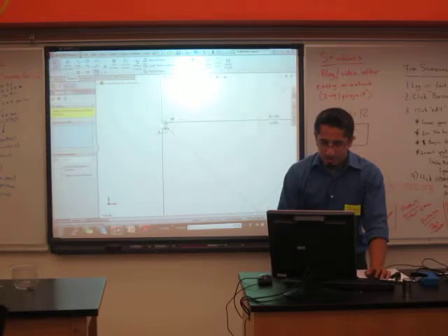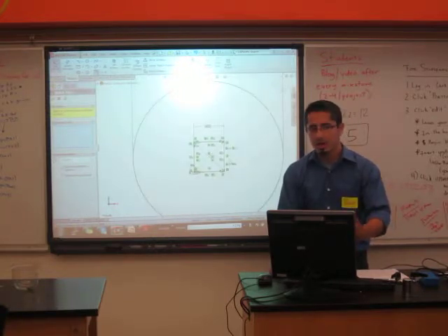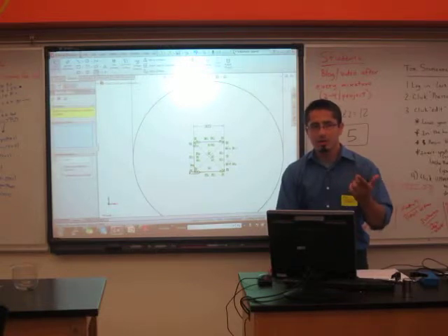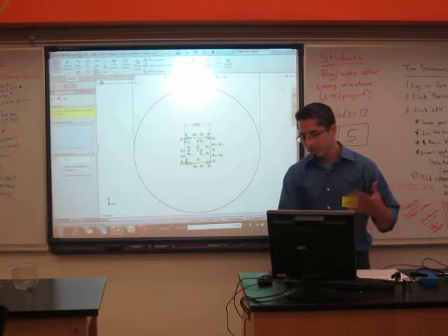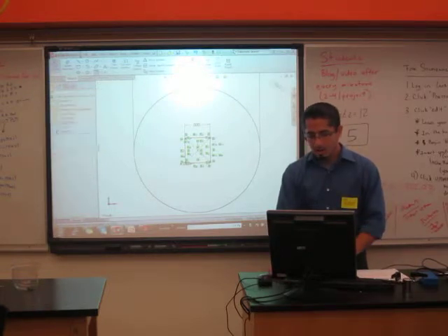So I got these little corners now that are allowing me to have a little round. Because when you're actually machining and cutting things, the cutting tools aren't square. They actually cut little rounds. So you want to keep that in mind as you get further along in your futures.